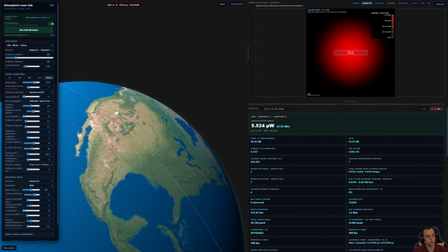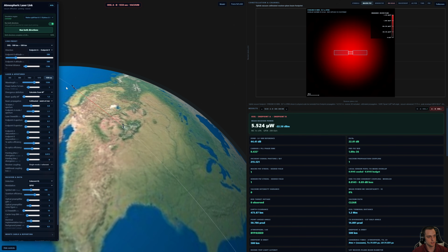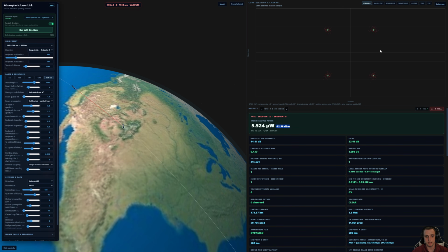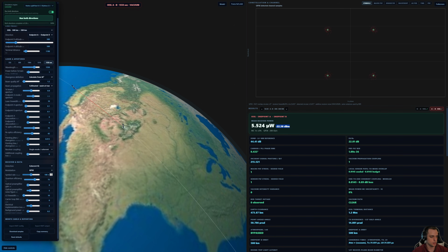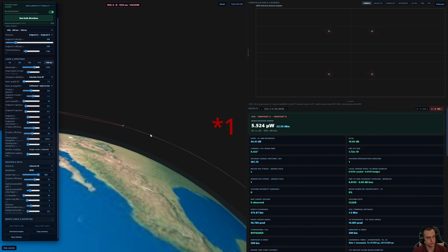Speaking of laser terminals, let's go through again and take a look at the Starlink scenario. So here is sort of a basic 1200 kilometer laser link. This is something you might expect. We have minus 23 decibels here. And if you look at our constellation plot, it's very clean. And so they could use this for 200 gigabit terminals or 400 gigabit terminals. This would be 400 gigabit. And the link seems like it would be perfectly fine. And this is very simple. You can just use the Friis equation because the turbulence-induced Strehl ratio is 0 because there's no atmosphere.